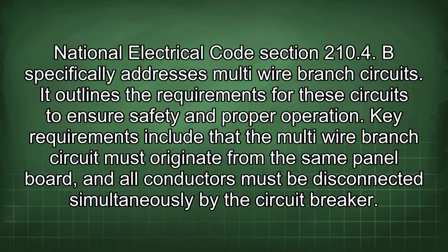National Electrical Code Section 210.4. This specifically addresses multi-wire branch circuits. It outlines the requirements for these circuits to ensure safety and proper operation. Key requirements include that the multi-wire branch circuit must originate from the same panel board, and all conductors must be disconnected simultaneously by the circuit breaker.